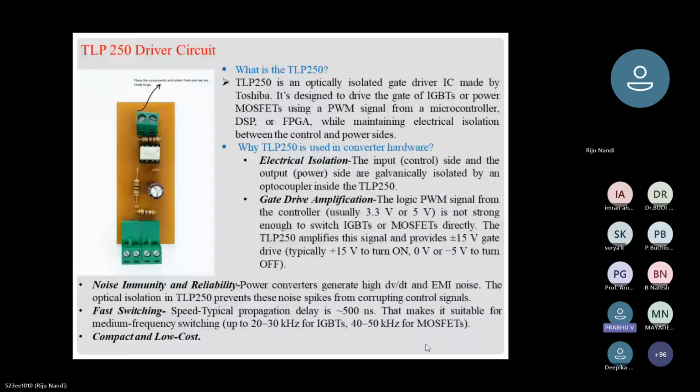Yeah, exactly, I'm asking that only, sir. You can see that the TLP250 driver circuit is available in Google also. Okay, yes, sir. I saw that they are prescribing 8 ohms, or sometimes 10 ohms, and then again 22 ohms in the data sheet itself.